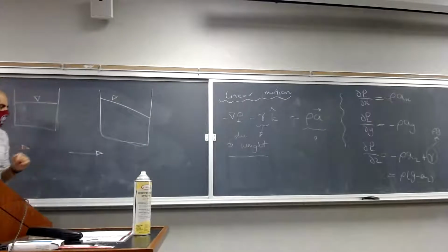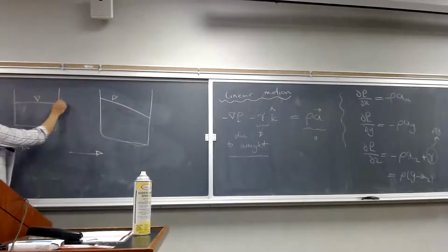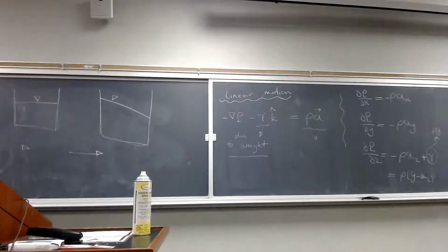Before moving forward, there is one thing we need to make sure we understand. The idea of the hydrostatic pressure was that if you keep the depth constant, and that's for the fluid at rest, right? We will have constant pressure lines. So as long as your depth is the same, your pressure on this line is going to be the same, which means your free surface pressure is constant, okay?